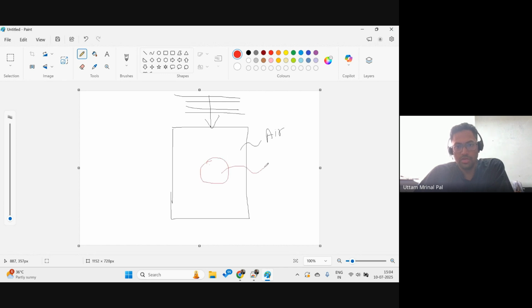This was silica glass, and this domain is a lossy domain. Because it is a lossy domain, we would actually see the rise in temperature, and because of the rise in temperature, you could actually see some kind of deformation. So we wanted to see how to do the coupling of electromagnetics with other physics.